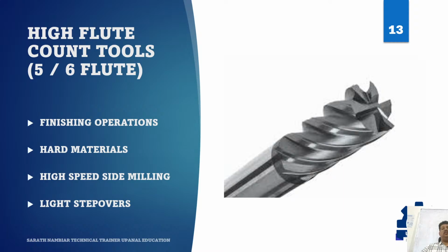However, there is a trade off. More flutes means less chip space. So these tools are not ideal for jobs generating heavy bulky chips in tight spaces. That is why these cutters are often paired with modern tool paths, lighter stepovers, and controlled strategies. We have to consider it a specialist tool rather than a beginner general purpose tool.